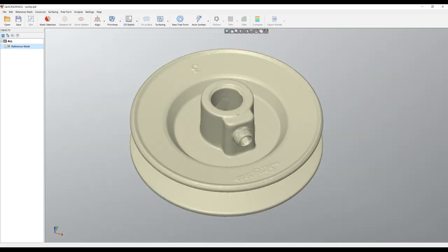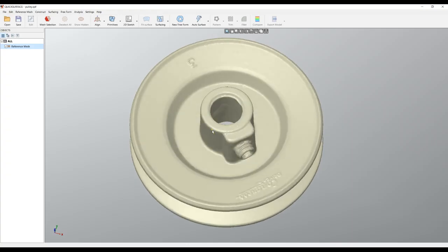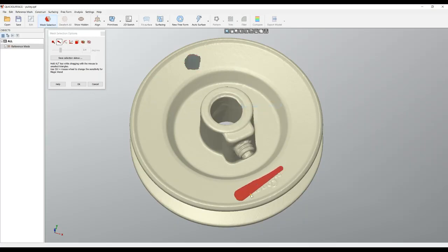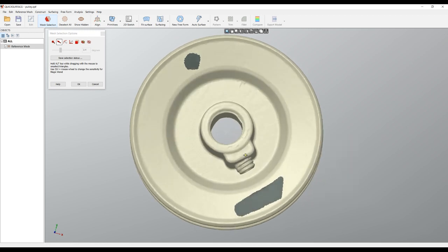As a strategy, I can get rid of the data that is not needed for my main profile. So let's make a mesh selection. I will use my brush tool. We'll make sure that the select through tool is not turned on, and I will just paint this, right click and hide selected. I will remove these from my current view so I don't use them.